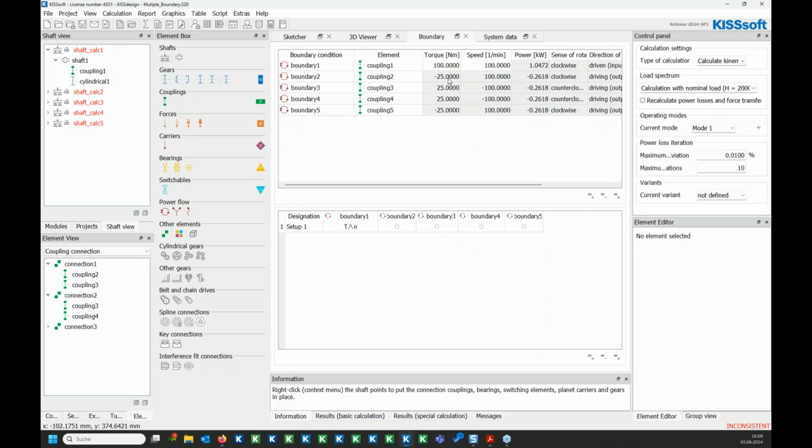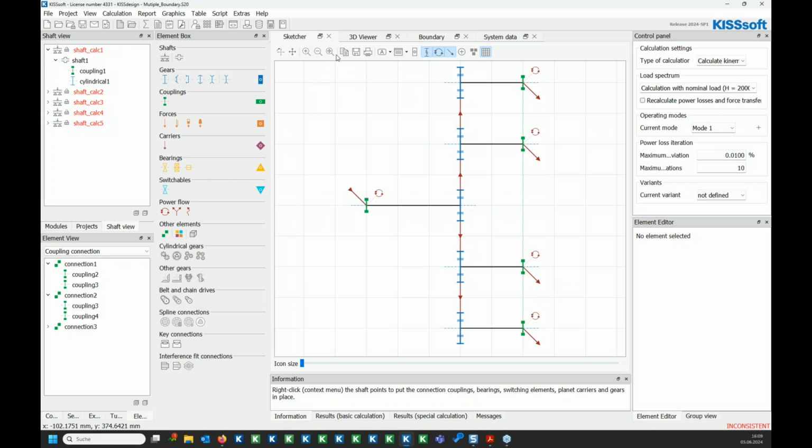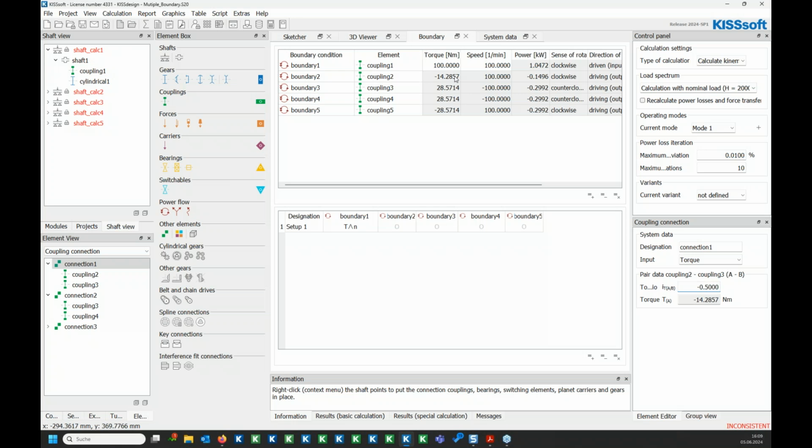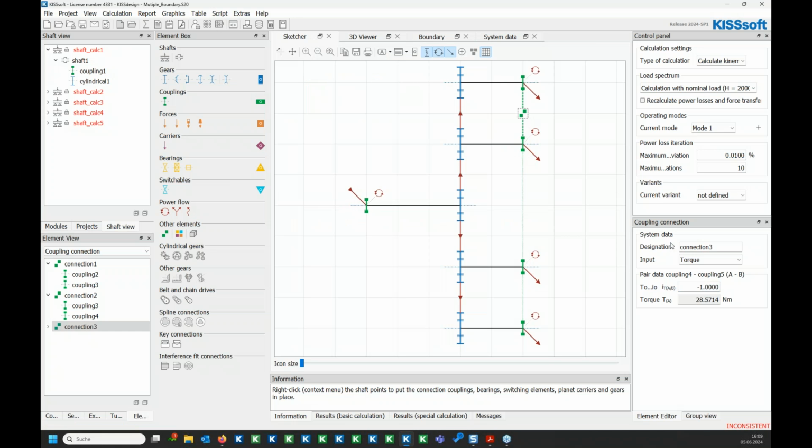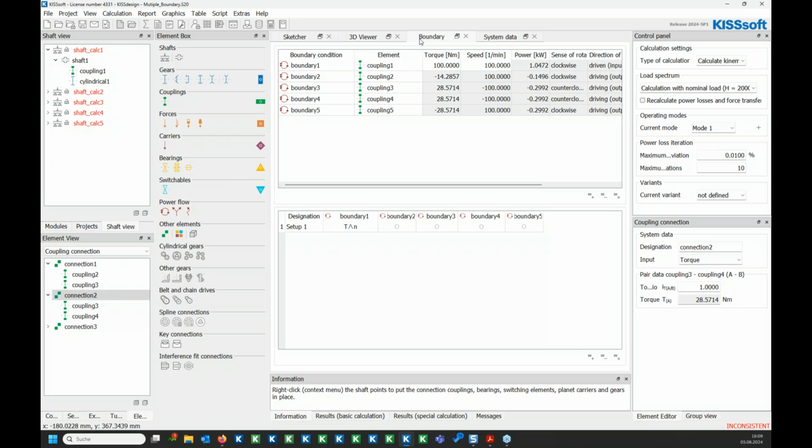And then if we check for boundaries, it's automatically calculating the equal torques on each side. Even if I say, between these 2, I would like to have, let's say, a 0.5 distribution for the torques, it's fulfilling this condition and calculating the rest automatically, so that the other condition of having 1 speed ratio here is fulfilled, and it's also calculating these options accordingly.